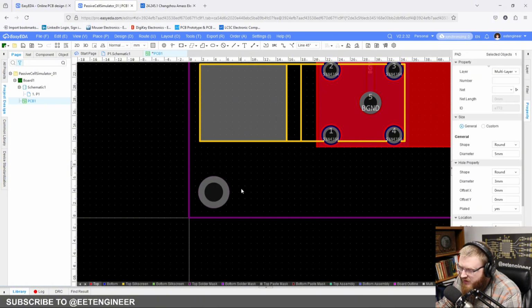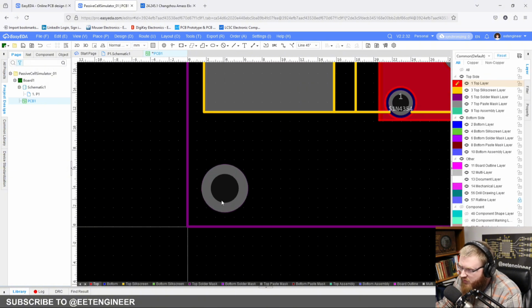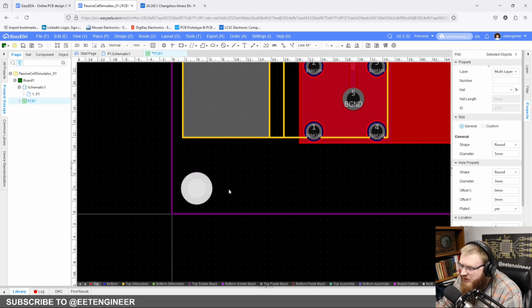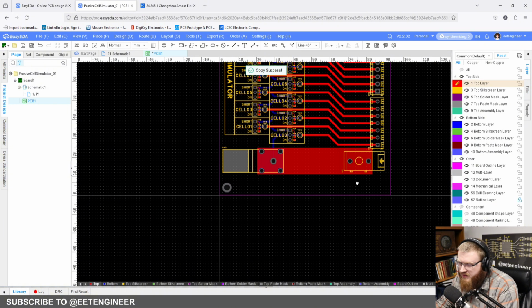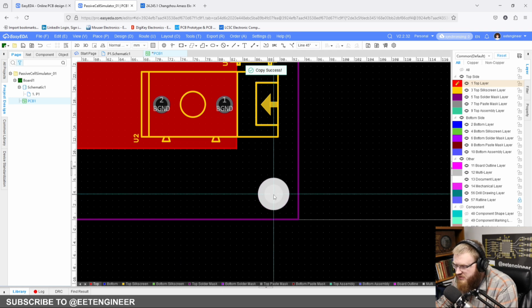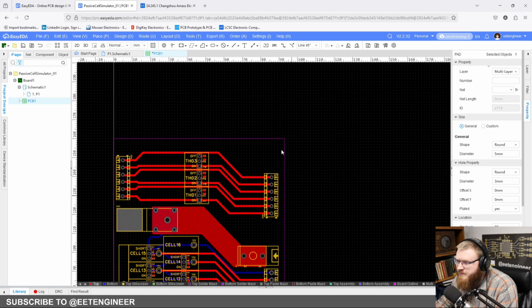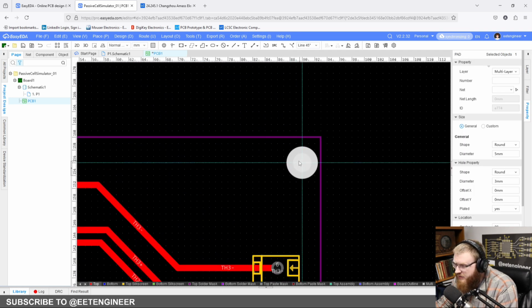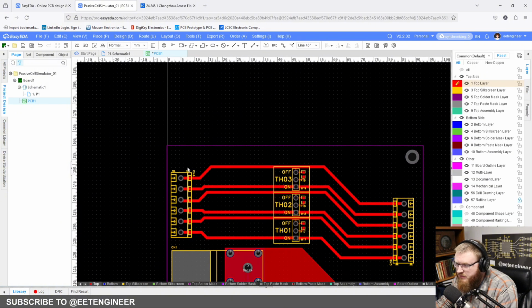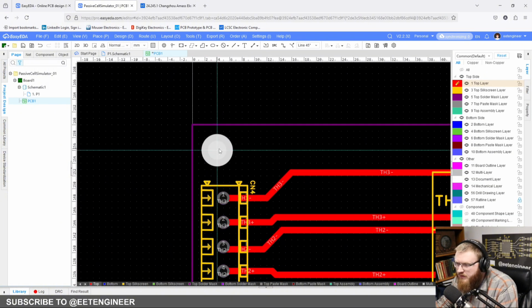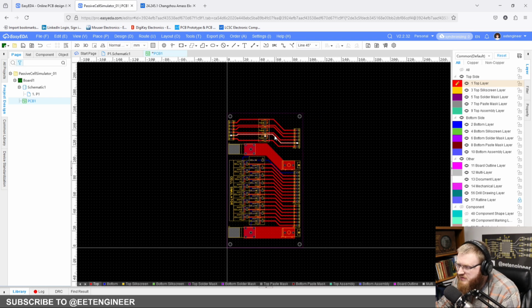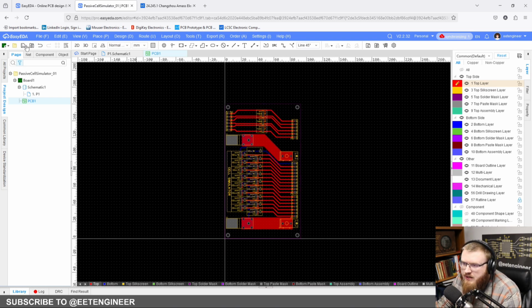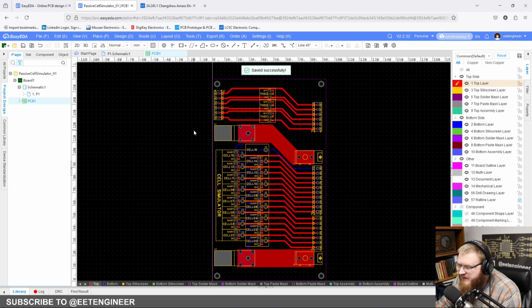And then we're just going to line it up. Again, since it's a 1mm grid and it's an even board, we can just line it up to where it's properly the distance away from the corner, just eyeballing it. And then there we go for an M2.5 or an M3 screw, depending on what kind of mounts you have. And then we'll just line that up there, and then line that up there, because again, in the corners, it's easy when you have everything on the same grid, or mathed to the same grid. So there we go. It looks like this is a completed board.